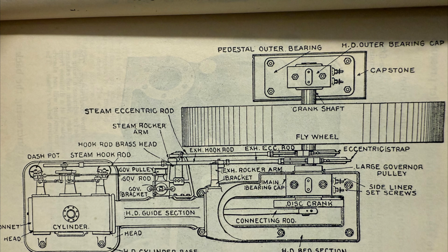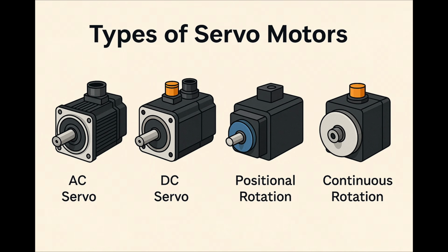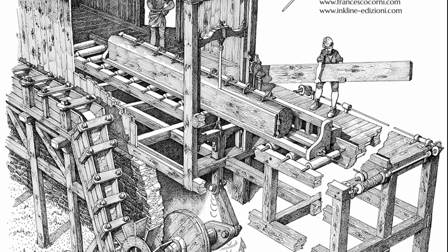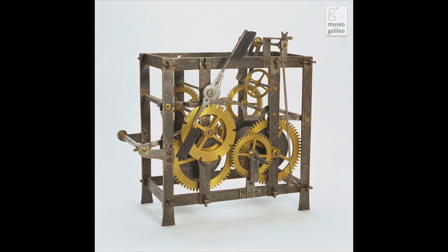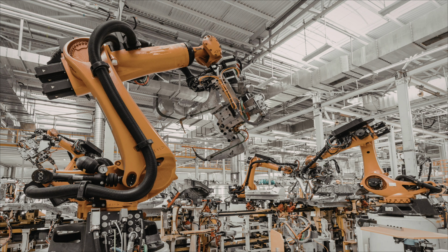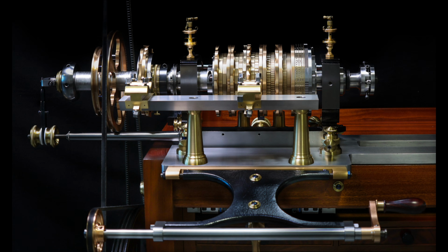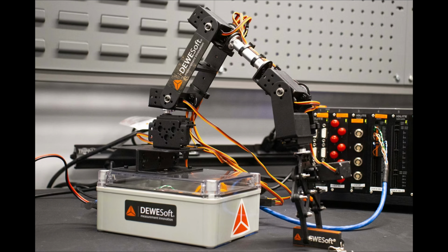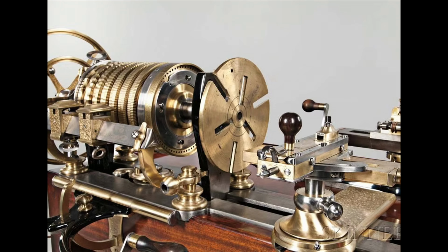Engineers definitely have options when building systems, but the choice to use cam-based versus software-defined symbolic memory is not arbitrary. The choice is driven by a consistent core question engineers ask. Do I want fixed, repeatable, guaranteed behavior, or flexible, changeable behavior? Fixed, repeatable behavior would suggest a mechanical solution. If you want various modes, adaptation to inputs or conditions, then you want a hardware and software solution. The cam can't be reconfigured later, but the software interprets inputs at runtime and adjusts.